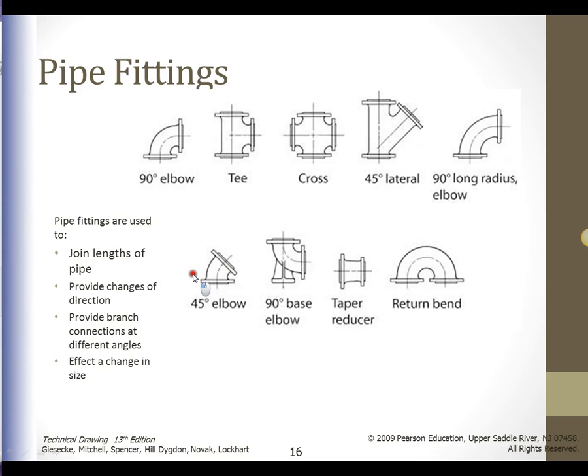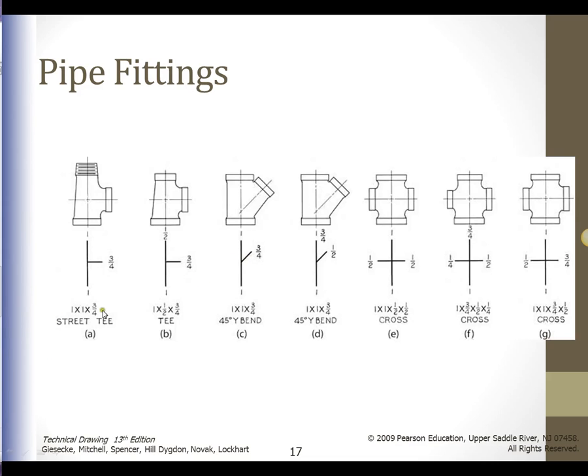All right. These are the various types of fittings. So you can see this one has a 1.5 inch by 3/4 inch. So a 1.5 inch comes in, and a 3/4 inch also goes out, however you want to look at this. Okay. So you can have a 1 inch by 1 inch. So this is 1 inch, and I'm talking about the cross. You could have a 1 inch going this way and 1/2 inch going this direction.